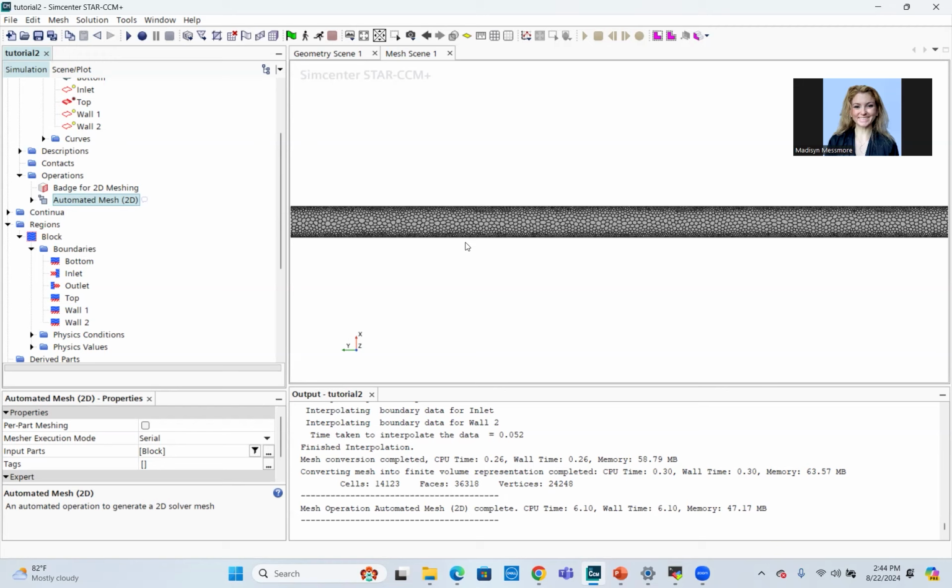And then the other one is computers can only store so much information about a single number. There's a whole science about it. It's really ugly. But effectively, you have to round the number at some point. And so the smaller you get, the closer to zero you get, the more impactful your rounding is going to be, if that makes any sense. So as you get a smaller and smaller mesh, your rounding is going to get more and more impactful. And you're going to be doing even more floating point operations because you're now going to have more and more equations that you're solving. And so it kind of gets compounded.